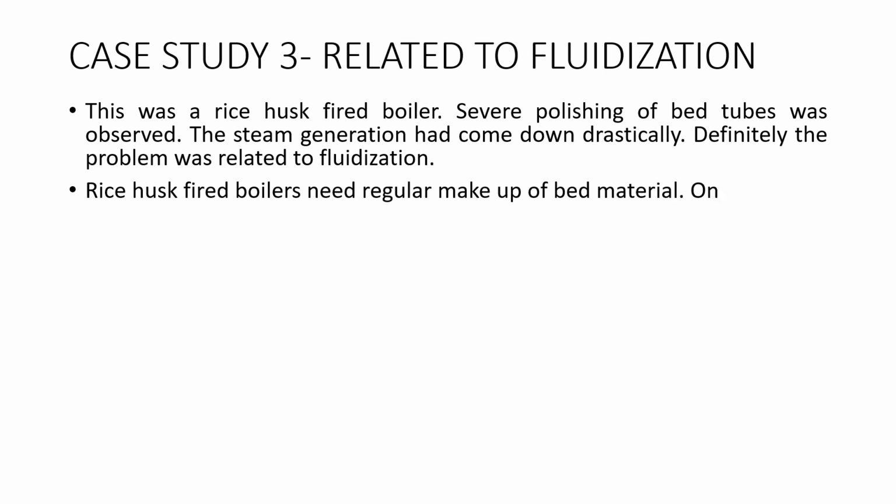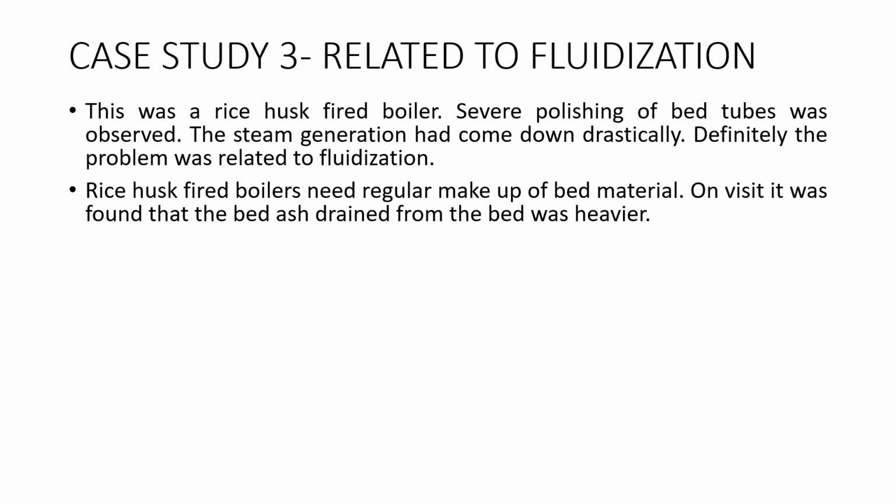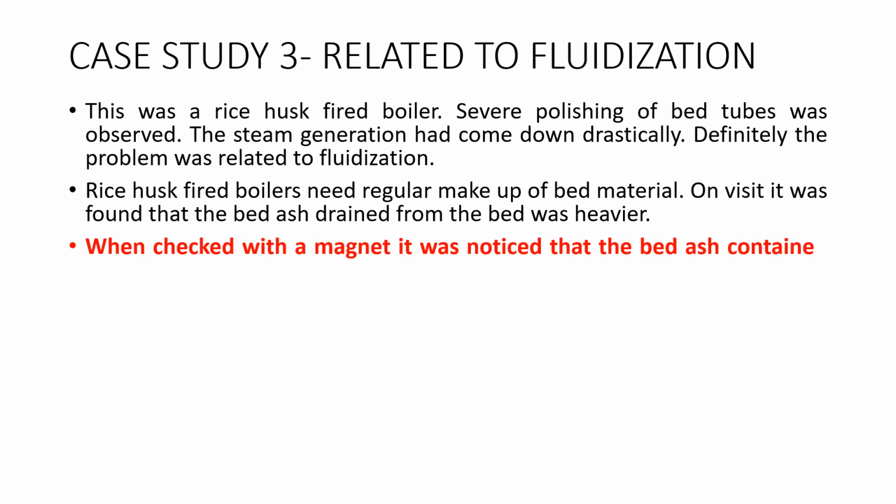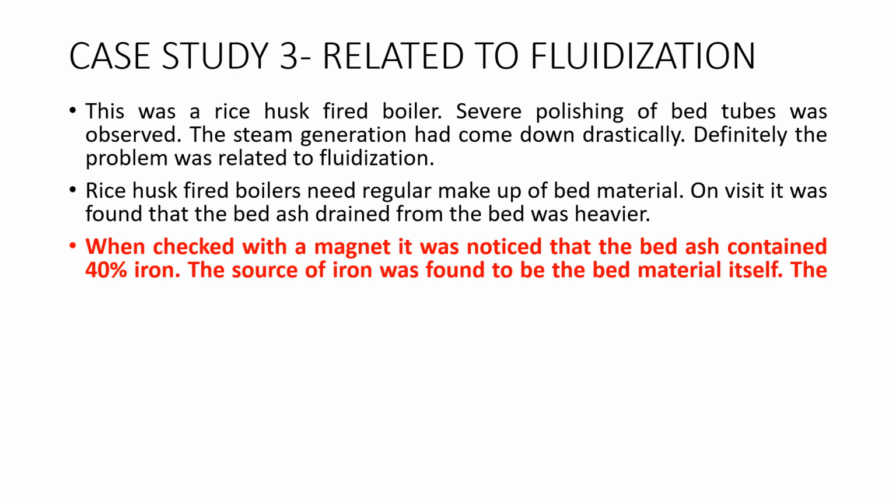Now rice husk fired boilers need regular makeup of bed material. On visit, it was found that the bed ash drained from the bed was heavier. So the bed ash was checked with a magnet, and it was noticed that the bed ash contained 40% of iron.